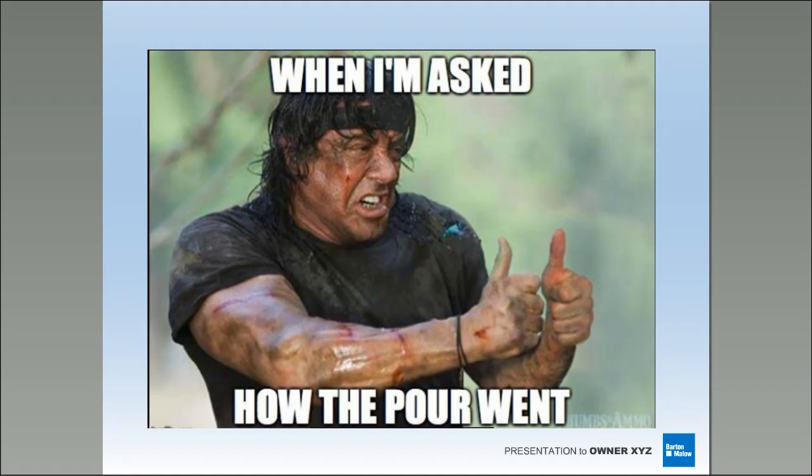Okay, Michael, how do you keep steel from the top becoming exposed, which potentially causes rust spots? If you're talking steel fiber, you shouldn't really have rust spots, because you should be densifying that slab to make it pretty impenetrable. If you're talking rust spots with wire mesh or something else, you don't want it near the surface. Steel fiber should not be rusting on you unless you've got a lot of moisture in that slab. It could be a bad choice from the owner.